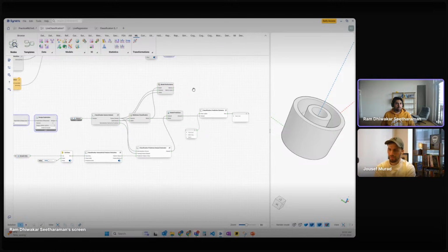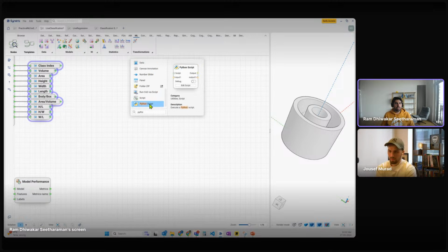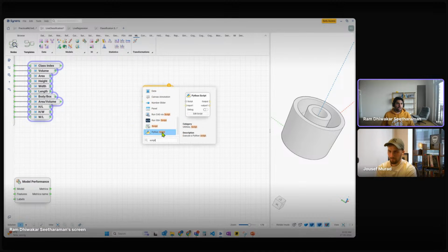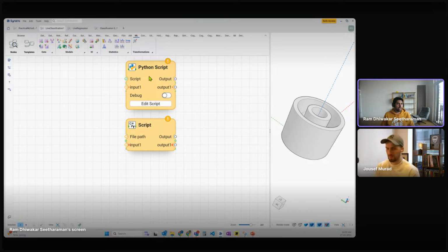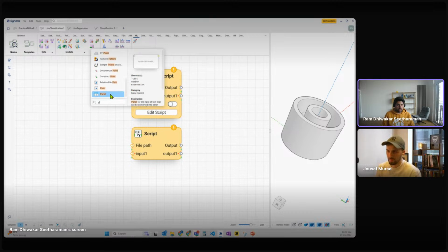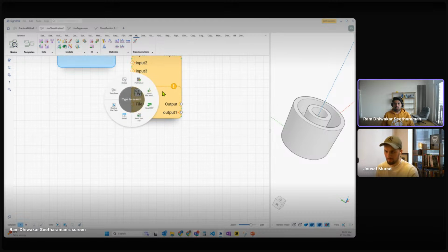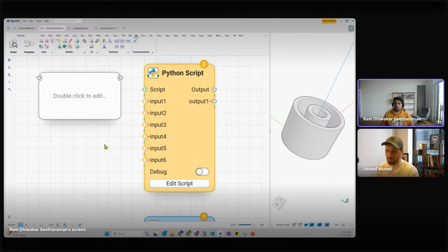Something that's cool also strikes me from the other question. If you're intermediate or advanced or even a beginner and you want to still go with controlling a lot, you can always plug in your scripts. If you want to have superior control over your models, of course, the aim would be importing your own scripts, running them in, and then you can also increase the hyperparameters here. Each of these inputs in the script could be a hyperparameter, and you can set up a DOE also for the script, so that you can automate the way the script optimizes.